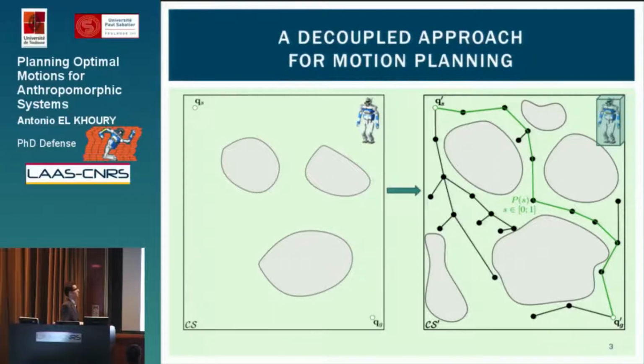could be arbitrary. Now, once we have found such a continuous path, which is collision-free, so we are avoiding the collision space regions, we can then move back to the original space of the system and either approximate or continuously reshape this path in order to transform it into a feasible trajectory on the original system. So here we are back to having the notion of time.